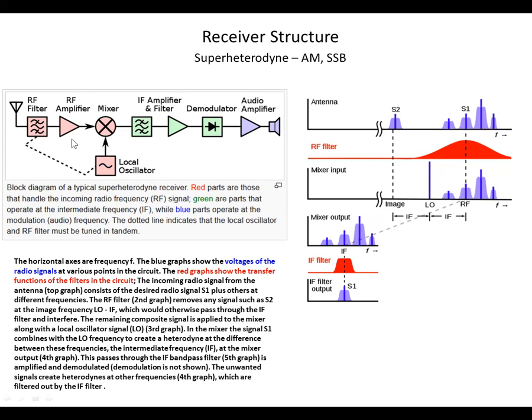So rather than trying to do that, what happens is you receive whatever frequency on those bands you're wanting to hear, and depending on the band, you bring it into the radio and use this mixer, and it shifts it to an intermediate frequency, which is the same frequency regardless of what band you are bringing the signal in from. So from this point forward, you know what frequency you're going to be dealing with, and the design can be much simpler because it's all going to be done at this intermediate frequency value. So that's how you can take a radio from 1.8 megahertz up to 50 megahertz and do all this neat stuff on it by doing this heterodyning process.